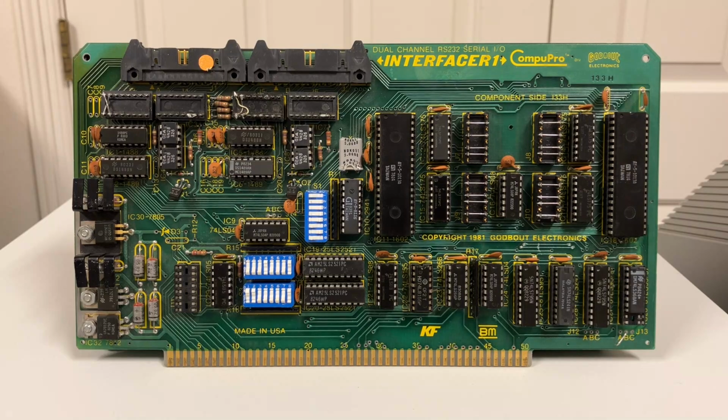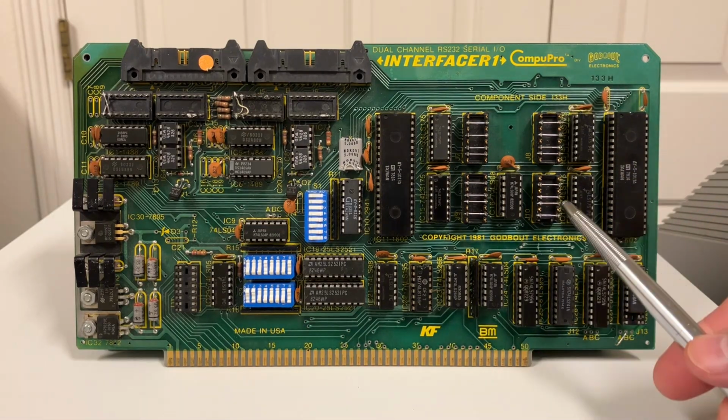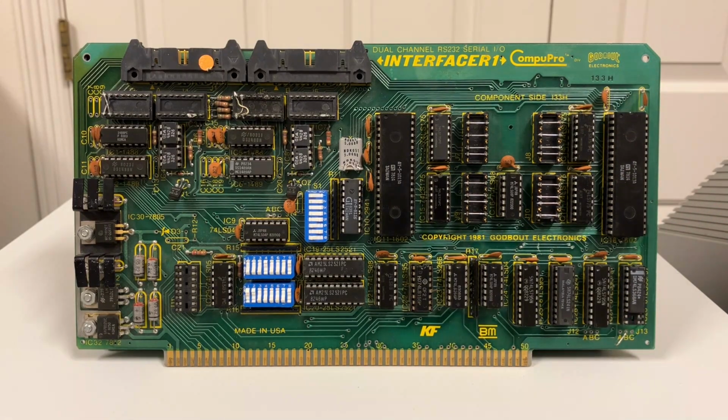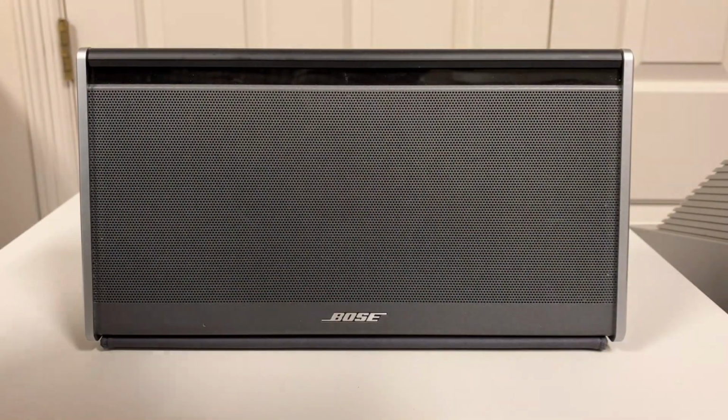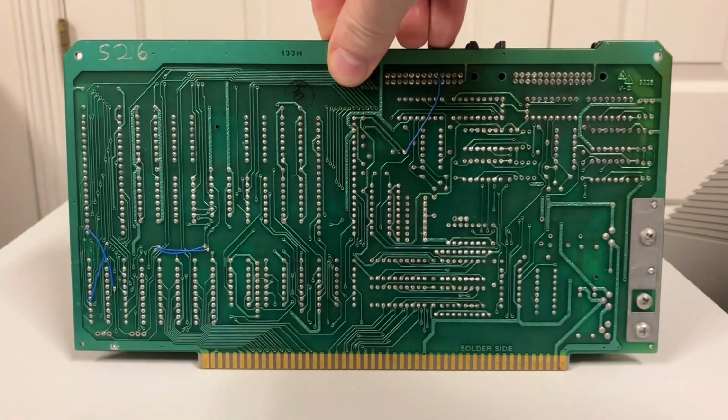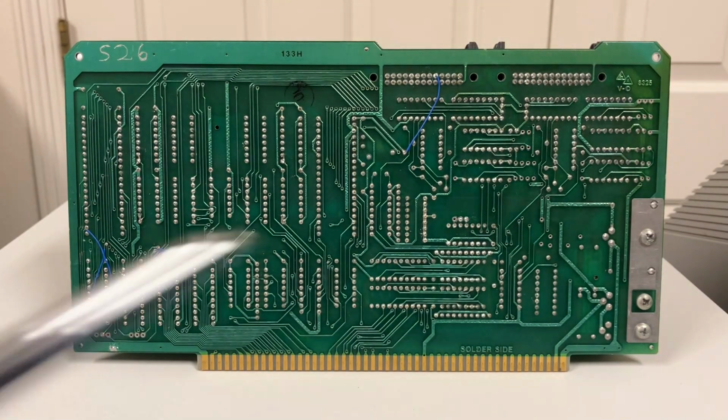All right, the next thing we need is to have receive data available on bit 0, and we need transmit data ready on bit 7. Now, you'd probably think that these jumpers are how we're going to do that, like we did with other boards, but those are for another purpose altogether. In the end, this board does not have a way to reconfigure the status register. So the only way we can do it with this board is to cut some traces and install some jumper wires. So that makes this a little less convenient than some of the other boards, but it's really not that hard to do.